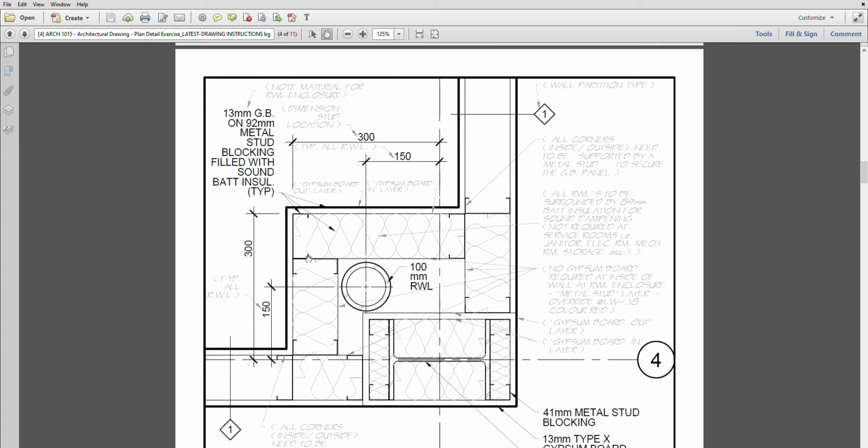And then you'll note what the item is that you've put in for the drywall enclosure. You'll also dimension where those studs are. You'll note the partition type that you're using. You'll note the framing and put the framing in place to secure the drywall at those corners.